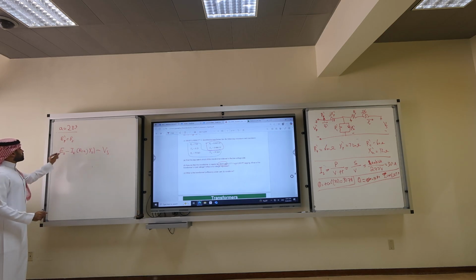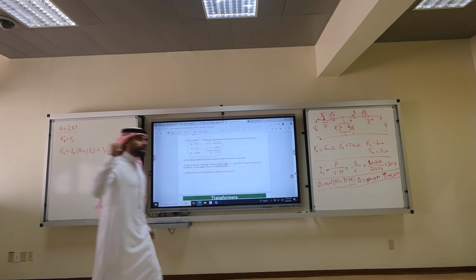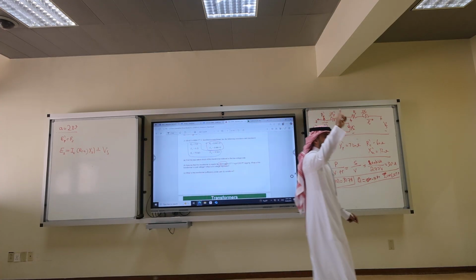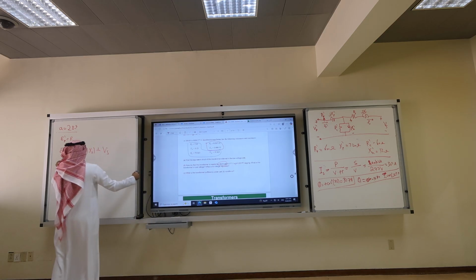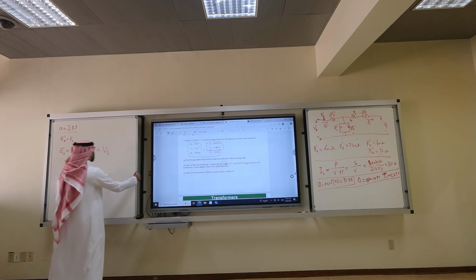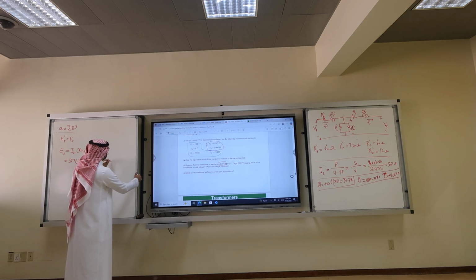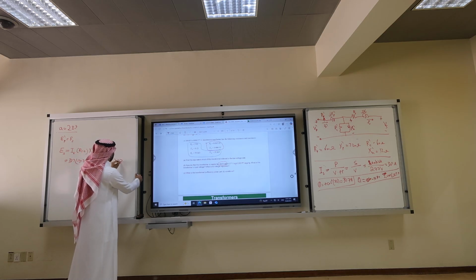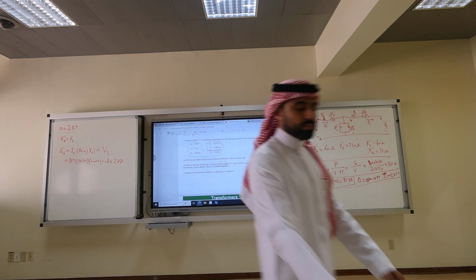A smart student would replace the negatives with an equal and a plus. And now you have KVL equation number 1. Plug in the numbers, calculators. A smart student already stored this number in the calculator, right? Correct? What is RS? 0.005 plus J 0.006, plus VS, it's 277, angle 0. No need to write angle 0. Calculators.